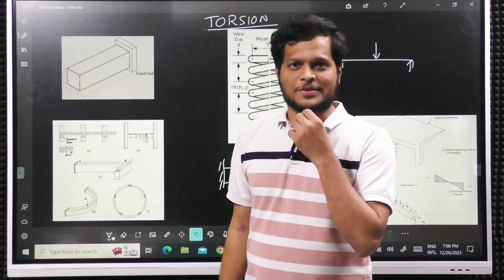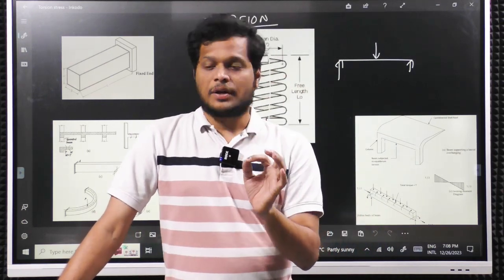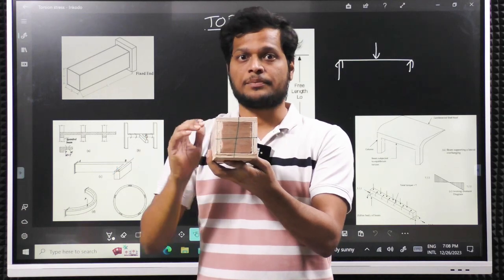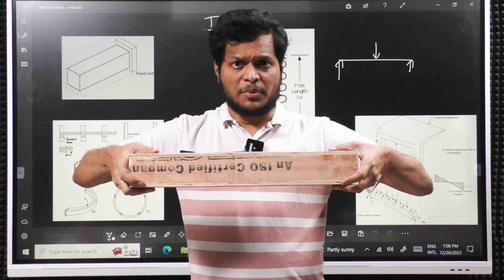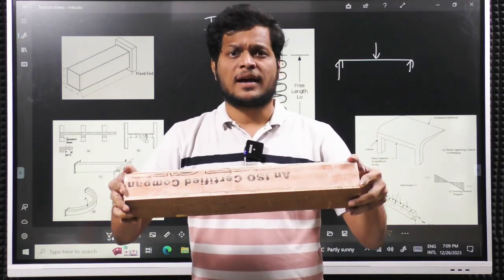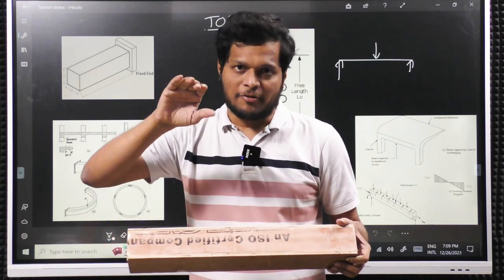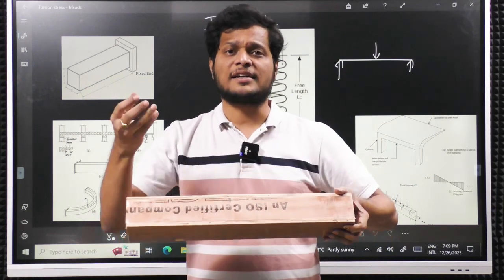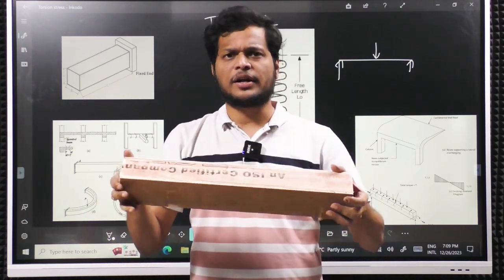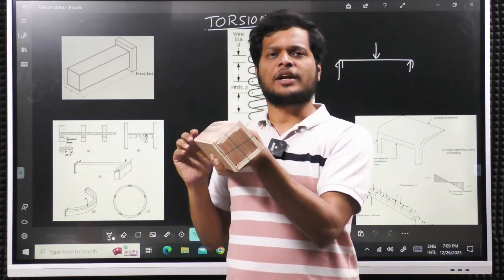Now how can we apply these rules? Let us see. In structural analysis, identifying everything is very important. In previous classes also, if you remember, we told you about the diamond section. This is a square section, not a rectangular section. If you are bending a square section with a moment, some x moment is required to fail this. Just by rotating it 45 degrees, I can save 30% of the moment to fail this. If I want to break this easily, just by rotating, I can save 30% of the effort. Why? The diamond section is 1 by √2 times the square in bending. Just by rotating, I am not changing material, I am not changing load, anything.